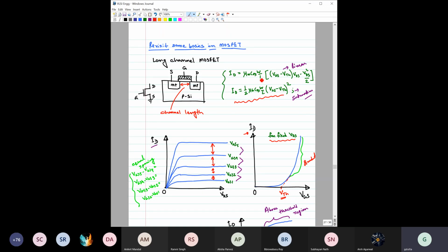If this transistor is operated in the linear region, then obviously the characteristics would be a little bit different, because here the ID is proportional to VGS, so it should be linear, right? If you see some region which is linear, then obviously it is in the linear region from this plot. If it is of this quadratic nature, then you should understand the transistor has entered the saturation region. Again, the entire thing will depend on this VDS and VGS value. So maybe for a particular VDS, it may look like this. If you change this VDS value, the nature of this curve will also change, right?